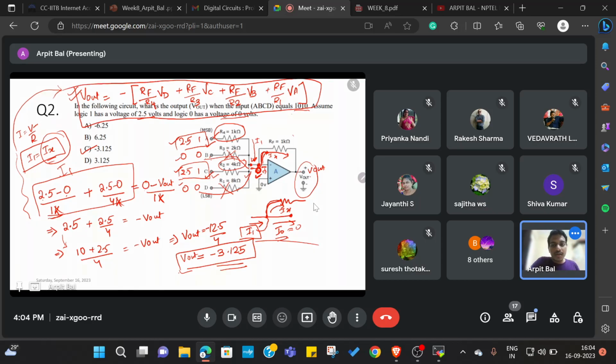But let's say you are stuck at a point where you think, why do I need to use this formula, how did this formula come up? At that point, always remember that the input of the op-amp being used is actually held at virtual ground. The property of the ideal op-amp is that it does not suck in any current, so I0 is equal to 0, and I1 is going to the output. So I1 is equal to Ix because there is no current going into the op-amp. So at this particular node you can use KCL, and you will arrive at the formula.